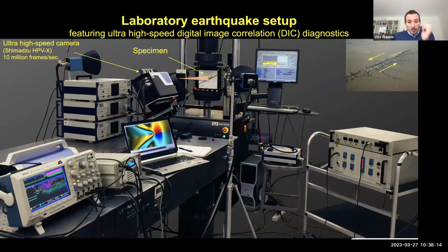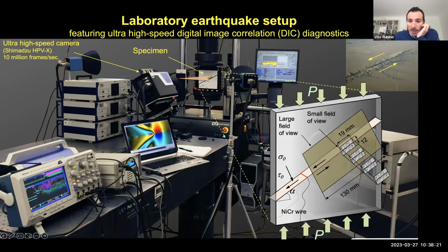Right, so let me show you the laboratory setup. The key ingredient is the specimen here, loaded in this press. Let me highlight it. The specimen is loaded uniaxially by a load P, which then produces a normal and shear level of pre-stresses along the inclined fault, which is cut along this inclined interface between two plates of analog material, which typically is either Homalite or PMMA, so plexiglass.